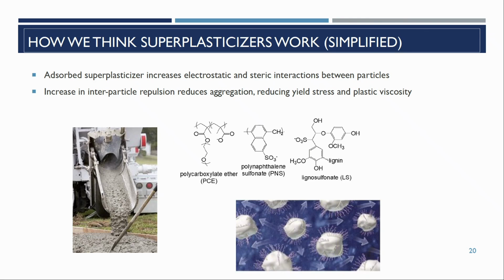Basically what you do is you take a dilute solution of a ceramic powder, you add the polymer dispersant to it. And then if you adjust the concentrations of everything just right, and you let it sediment, you'll see different equilibrium sediment heights. And that will correlate with the extent of aggregation, which will correlate with changes in interparticle potential. Really, all we were looking for was something that was kind of pointing us in a direction. We could do a rank ordering of the dispersing effect, but this was definitely not brilliant.